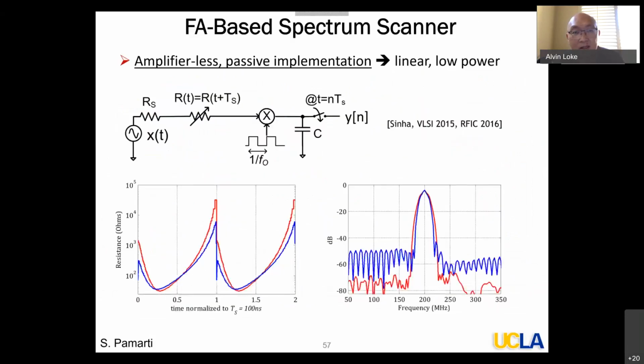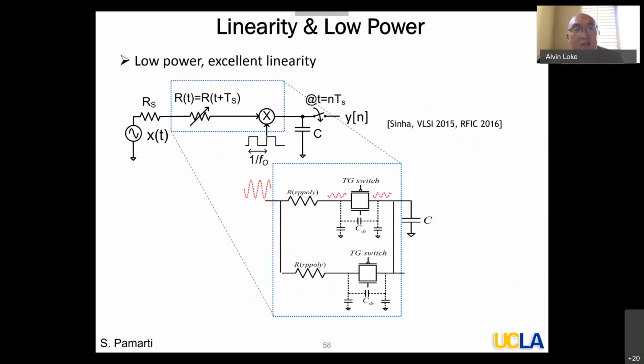We do the obvious symmetry-based techniques. For example, if I have a transmission gate, then I try to make sure that those things are balanced and things like that. We did not have to do anything special. One thing that we did do is that if the parasitics also vary in time, that complicates the effective filter shape. You can design for it, but the design becomes complicated.